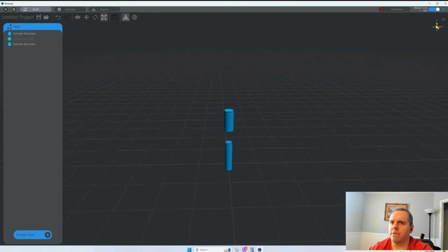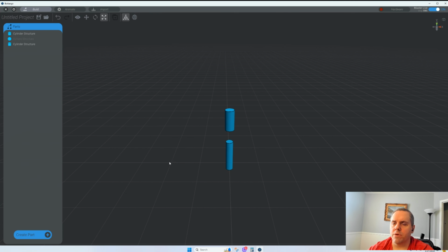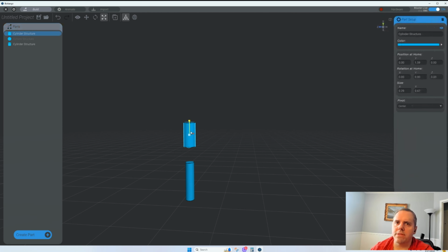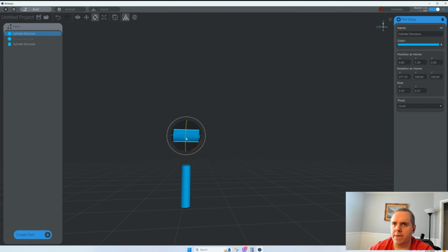I want to look at it from, okay, get my orientation here. Now let's go look at it from the side. I want to tilt the thing forward because the eye's not looking straight out of the top of the head, right? So click on E, or type E on your keyboard, and spin this thing horizontal, right? Looks good enough to me. Now W, and then we'll drag this thing out. Yeah, it looks like it's looking down a little bit.